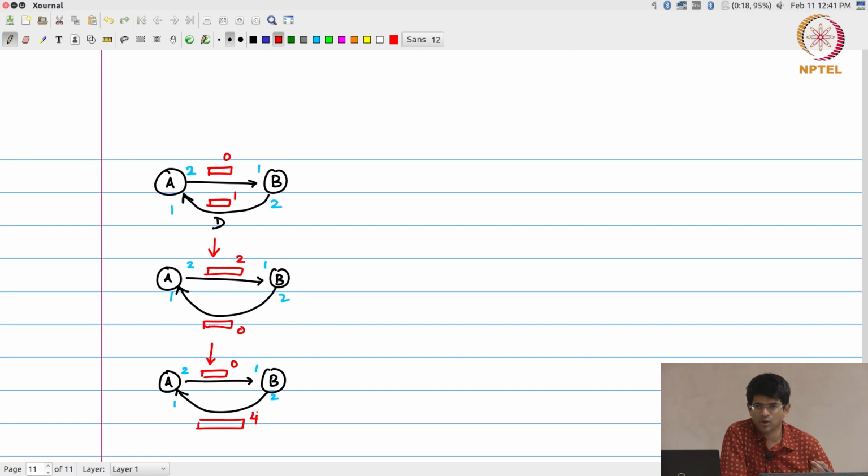Okay. So you see where the problem is. Essentially what ended up happening was that this set of values for the production and consumption parameters is unstable. So the FIFO will eventually overflow, no matter how big you make it. No matter how big you make the FIFOs between A to B and B to A, at some point if I carry on like this, they will end up overflowing.